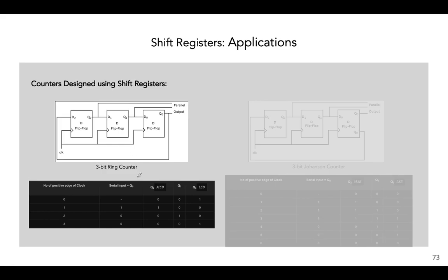Okay, so this is the basic arrangement of your shift registers. We have 3 D flip-flops here. We have the clock like we used to. This is a serial in. Technically, this is a serial in, serial out register with two important additions, we can say. First is, this is the output line, right?